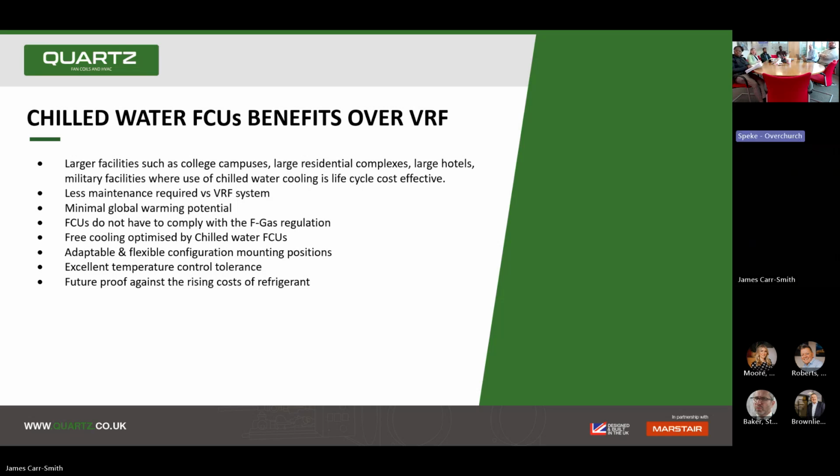Again, it's a sort of recap really of the slides we've just covered. Chilled water tends to be more beneficial when it comes to large installations. So it could be large residential, it could be large commercial, hotels. We talk about the life cycle cost effectiveness there. So yeah, we can send some of that information over. Less maintenance is required than a VRF system. It hasn't got to have regular F-gas checks, once a year or multiple times a year, depending on the charge of the system. It has a minimal global warming potential, and doesn't have to comply with the F-gas regulations.